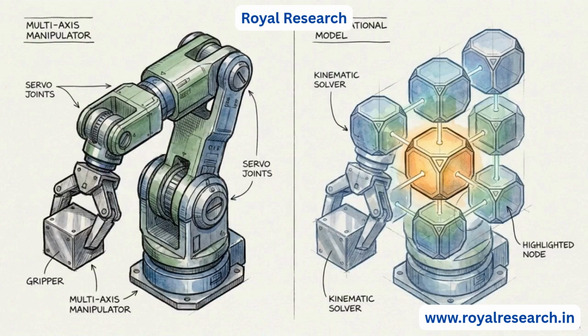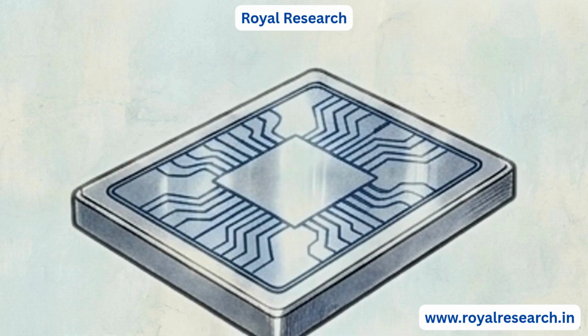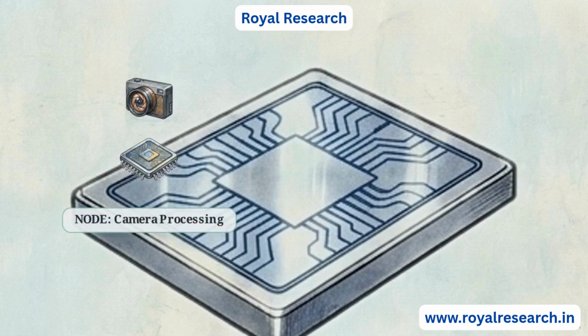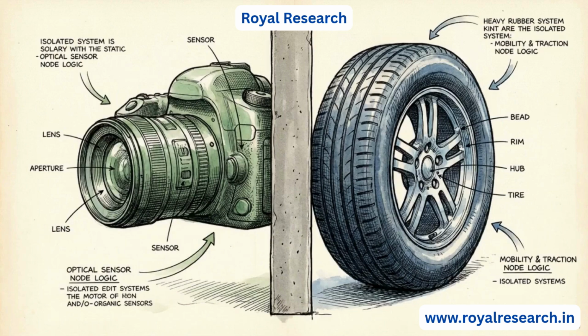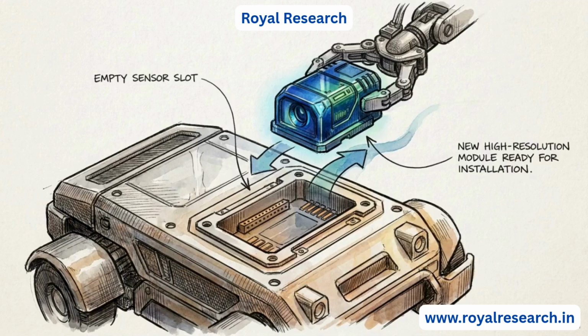We can build the ROS architecture from its fundamental building block, the node. A node is a discrete, single-purpose computation process running within the robot. This specific node might spend its entire life cycle ingesting and filtering a raw camera feed, isolated from other tasks. We can then introduce a second node dedicated to a different mechanical function, such as wheel motor actuation. These units remain strictly isolated. By design, the camera node operates with zero awareness that the motor control node even exists. This modularity allows developers to swap, upgrade, or debug individual hardware components without affecting the rest of the machine.